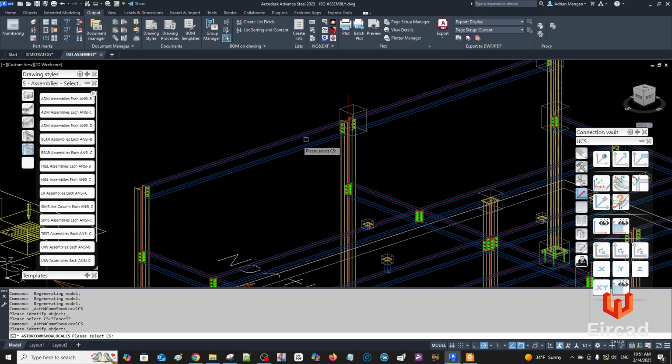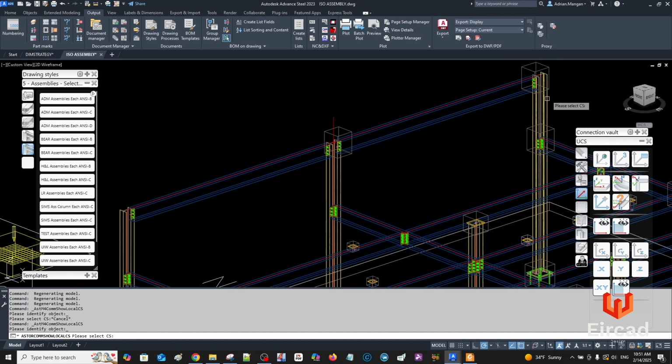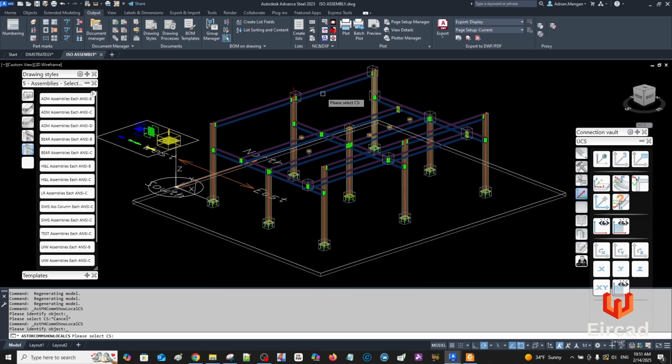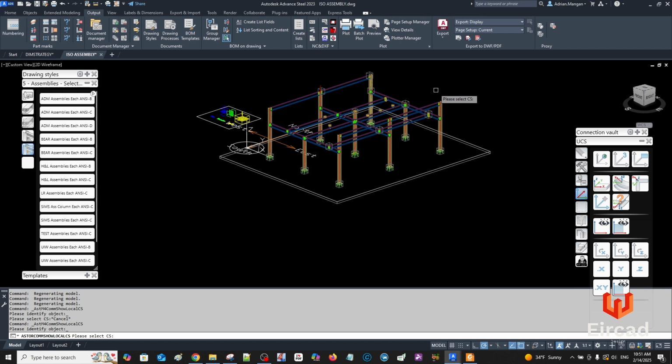Now these beams were created by drawing this beam over to here somewhere. Then I extended it to the column, and then I split it in the middle. That is how I create beams. I'm sure some people will disagree with me and do them a different way. That is how I like to do them, so I know that they're snapping correctly. I'll actually show you what I mean.